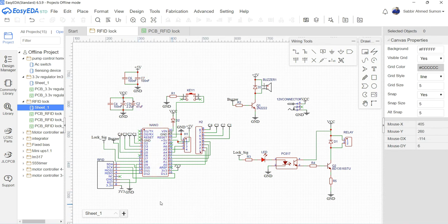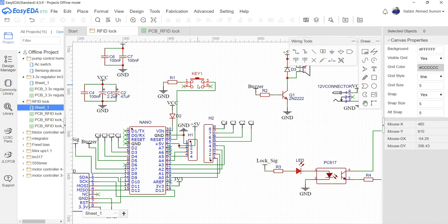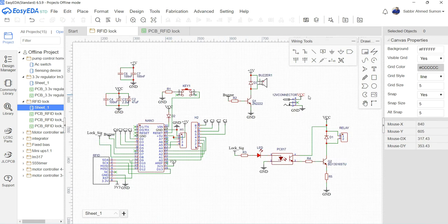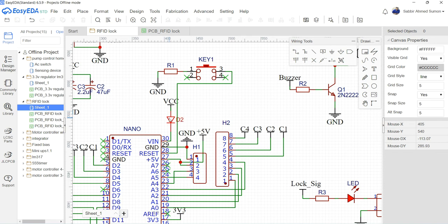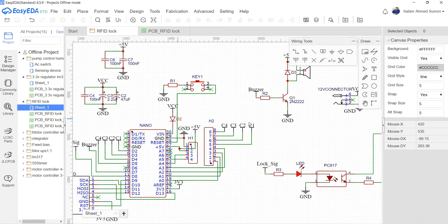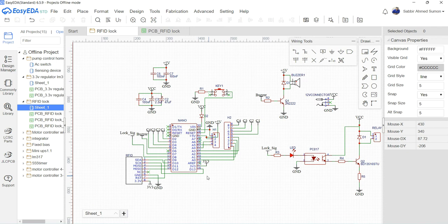So let's jump into the deep. Here I have connected a reset pin. The Arduino reset pin is active low, so it is connected with ground across a resistor, and the VCC is the power input of the Arduino. I have connected a diode across it so that there is no loading, or less loading you can say, on the 5-volt regulator of the Arduino.